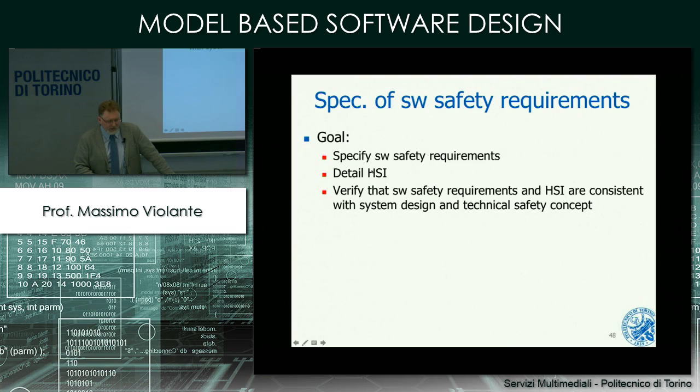Then you have to specify how your software will interact with the hardware. So this HSI stands for hardware software interface. So you have to specify which portion of the hardware you're going to use to provide safety. Think about the watchdog. The watchdog is a hardware device provided inside or alongside a microprocessor. Who is going to program that? Who is going to use it? Who is going to trigger the watchdog to start counting, and who is going to react on the expiration of the watchdog? These are all elements that you have to specify here.